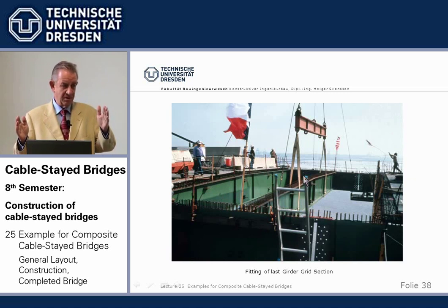The 2 beam halves were moved back at the towers. You remember we had there these corbels, some joints. Put a check in there, pushed outside. So the piece, the whole half beam, moved to the outside.